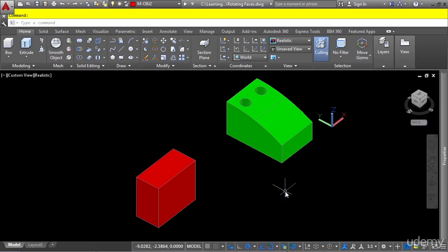When you rotate faces on a solid model, you either reorient the selected faces to a new location on the model by spinning them around an axis, or add material to or remove it from the solid model. If you select all the faces that represent a distinct aspect of your solid model, you relocate and reorient those faces. Examples of distinct aspects are holes, openings, and protrusions. By selecting only a few of the faces, you add or remove material as you revolve the face.